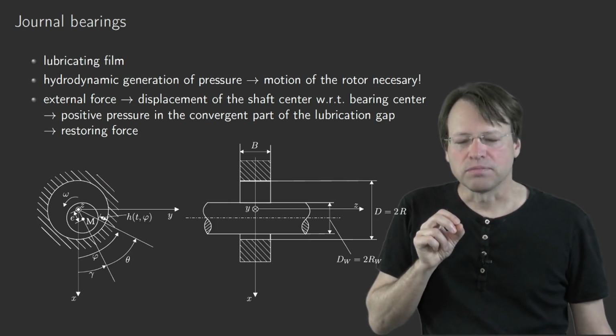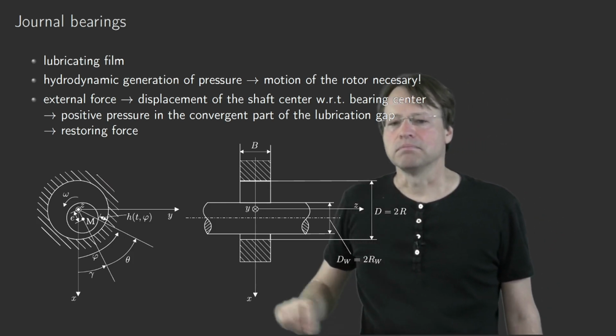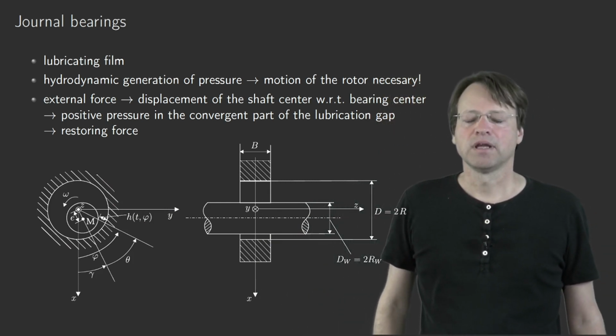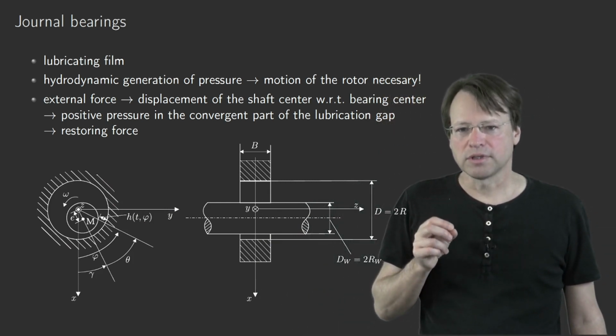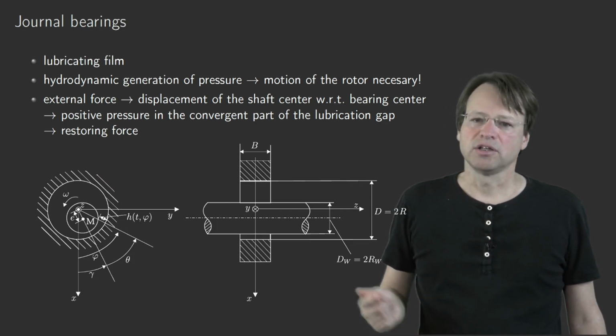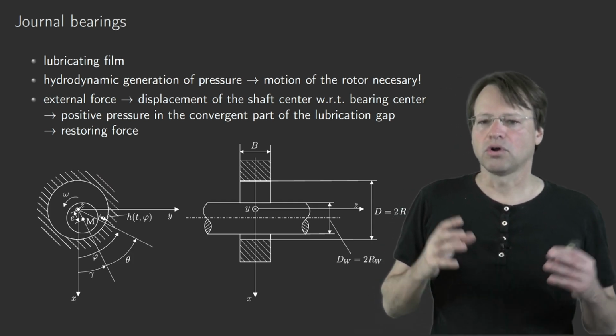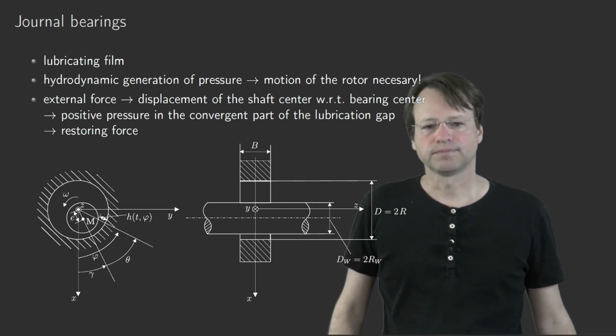And the influence could be such that the motion of the shaft becomes unstable. So hydrodynamic lubrication can lead to instabilities of the motion of such a rotor.